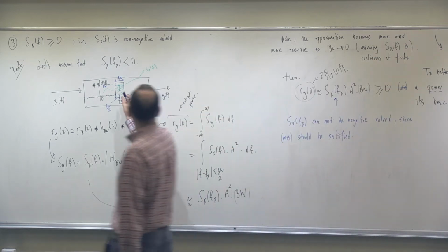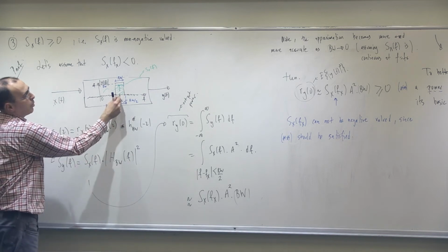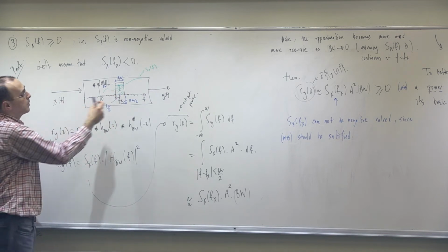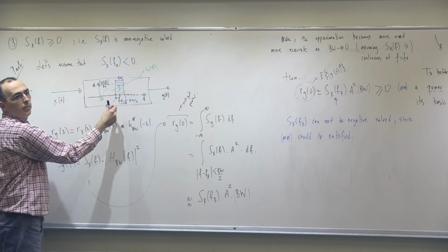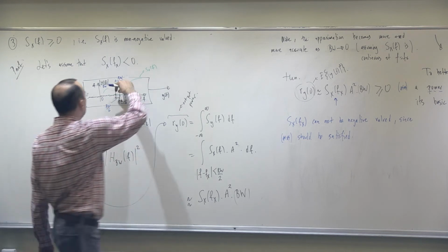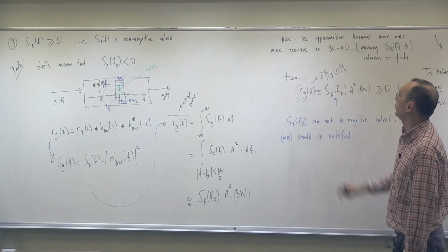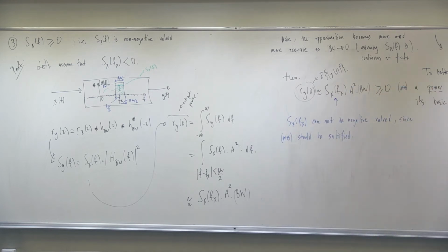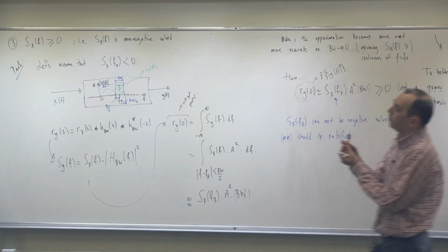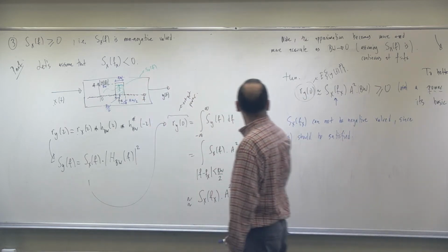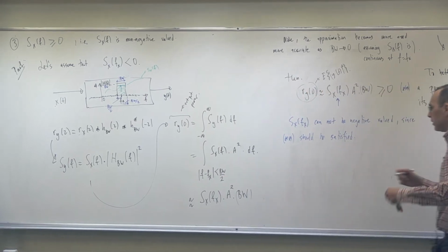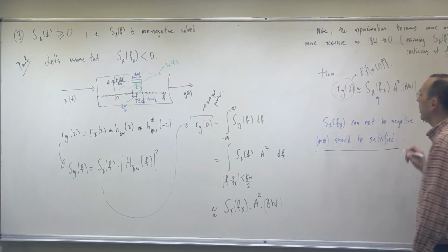Because at any frequency that my friend selects, I can always construct an imaginary, abstract filter with very small bandwidth. So I can always have only that frequency component passing out, and that will be the power of that process. Am I right? So that should be positive, if I make tiny and tiny filters, tiny bandwidth of the filters. So that is the end of the proof.